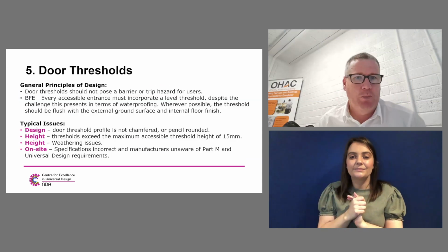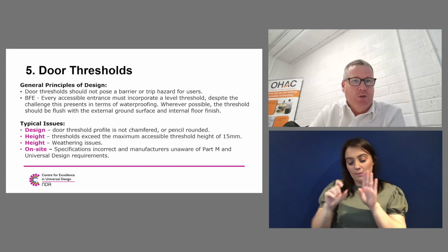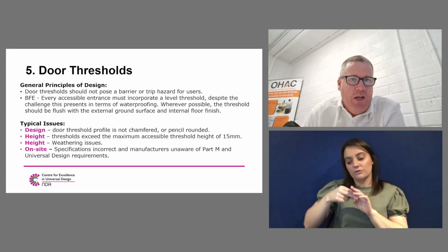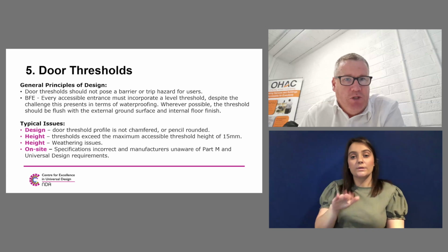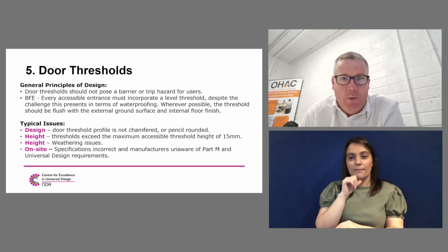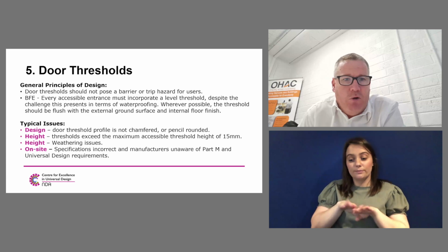So door thresholds should not pose a barrier or trip hazard for users. And in Building for Everyone, the general principle of design, every accessible entrance must incorporate a level threshold, despite the challenge this presents in terms of waterproofing. Where possible, the threshold should be flush with the external ground surface and internal floor finish.